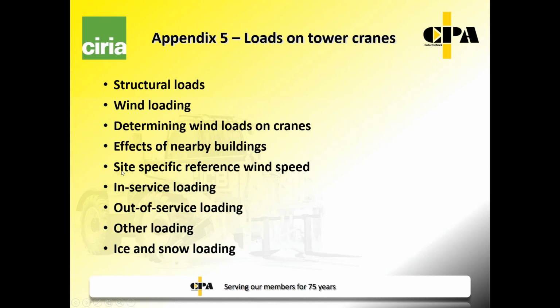If you have a particular issue with wind speed in the wind region that the site's located in, it may well be worth carrying out a site-specific survey so that you can determine whether the topography and location of the particular site allows a lower reference wind speed, which obviously will have a significant effect on foundation and tie loadings.